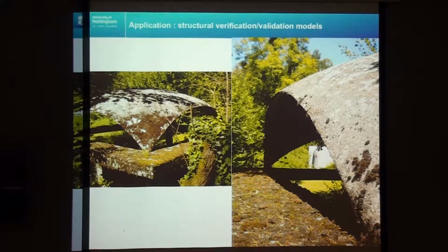This is the model that he made of the Bellinzona shell, which is about 30 meters by 30 meters. And this is in the grounds of the office, at 1/10 scale. And the thickness of the shell is just 8 millimeters. And that was built at approximately the same time as the full-size shell. And this doesn't have any pre-stressing in the corners, yet it's subject to exactly the same load as the full-size shell. So he kept this as a sort of reminder that as long as this would stand, then the full-size shell should also stand.